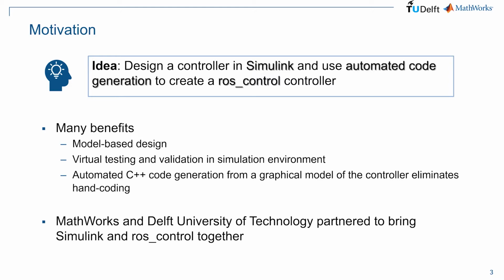And what we get by doing this is obviously we get to use Simulink, so we get to use model-based design principles for the design of the controllers. We are able to actually test it in simulation and validate that the controllers work in that simulation. And in the end, we press a button, ideally, and we end up with the code that represents the same graphical model, but then in a ROS control package.